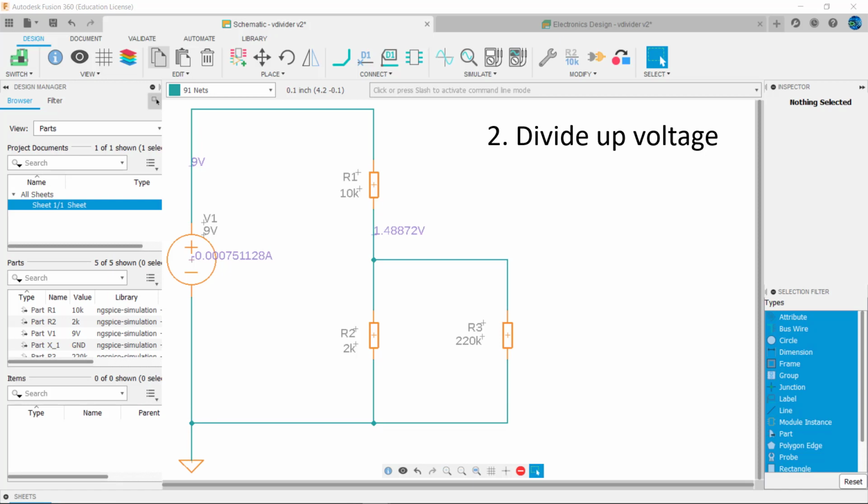But what if you have to connect a 1 kilo ohm load across R2? Is there anything you can do to keep the voltage across R2 and R3 around the desired 1.5 volts? Yes. Simply make the voltage divider output stiffer by lowering the values of R1 and R2.